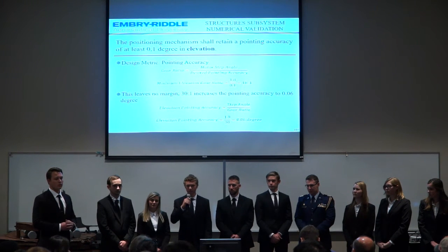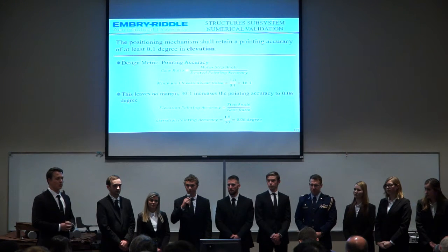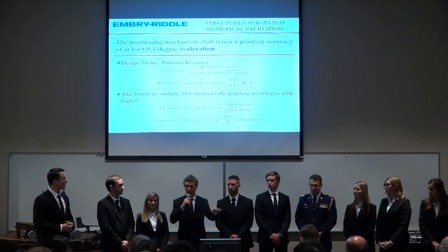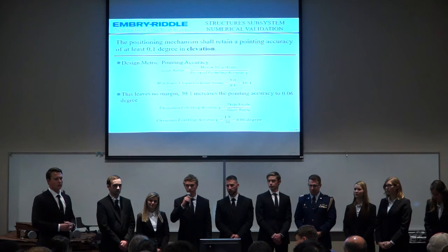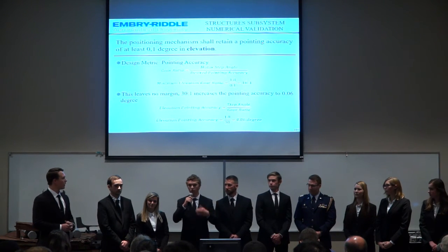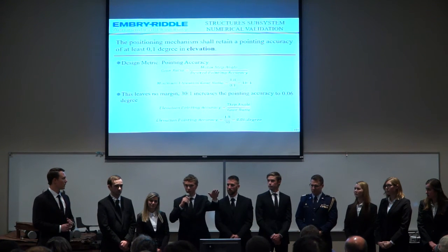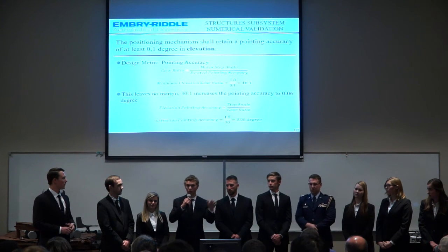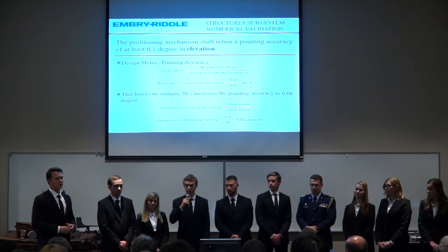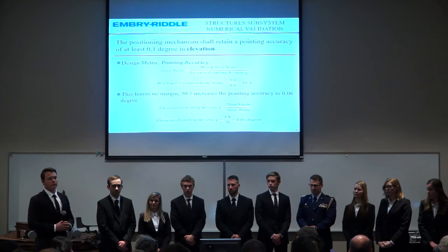Excellent. So are you planning to have some feedback on that, like with an encoder or a potentiometer? As far as where the barrel is oriented? Yeah, because with a stepper motor, usually most of the time, you just keep counting steps. Right, and we'll also have that barrel position determination, a 9 degree of freedom IMU on the edge of the barrel, and that will be able to give us feedback as to not only how many steps we thought we did, but where the barrel position actually is. Okay. Yeah, very good.